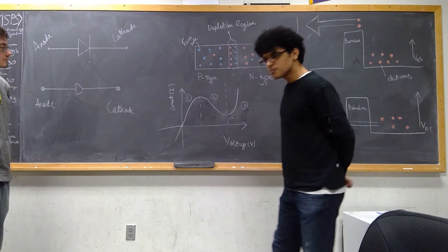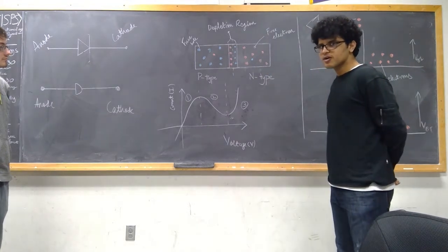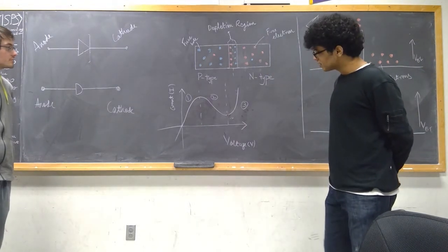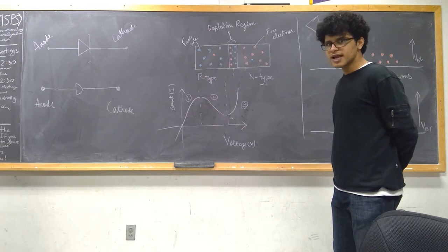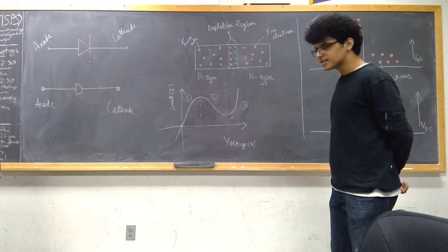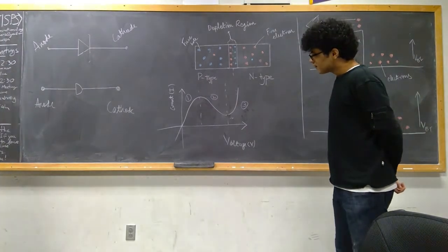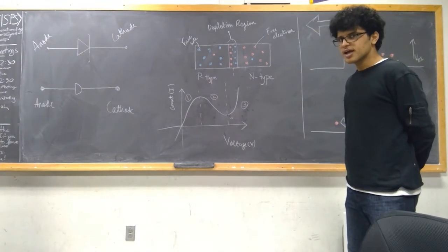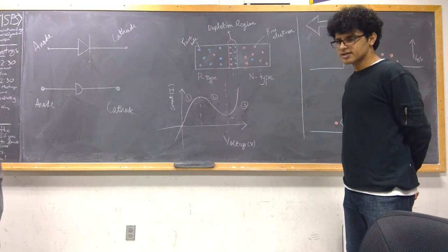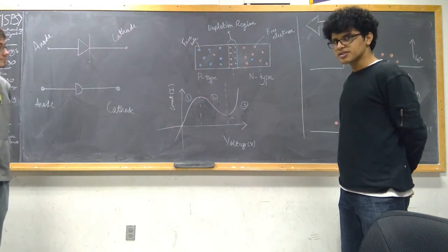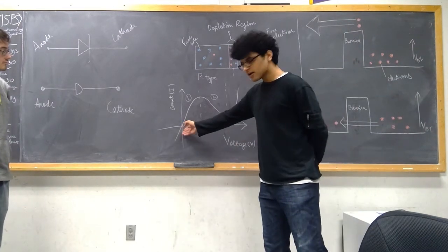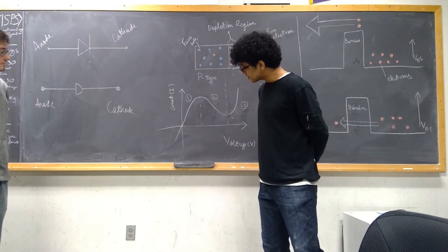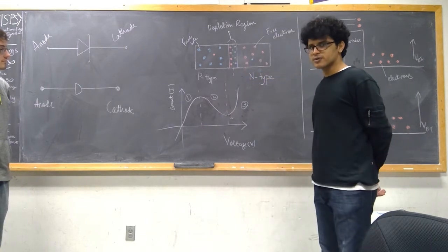These three regions make up the forward bias of the tunneling diode, as the voltage applied between the anode and the cathode is positive and greater than 0. When a reverse bias is applied on a tunneling diode, it behaves similar to that of a Zener diode but with 0 cutoff voltage. This is the characteristic of a tunneling diode which helps it to switch so quickly in high frequency circuits.